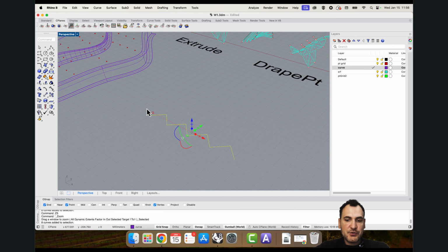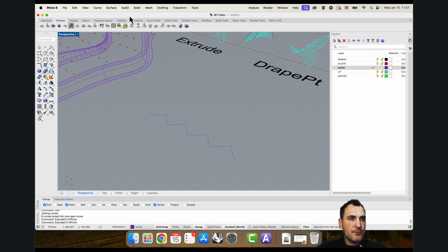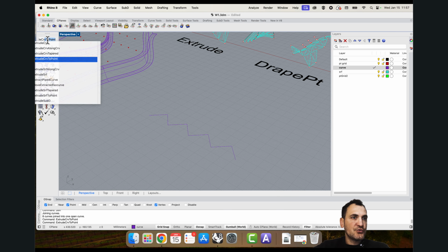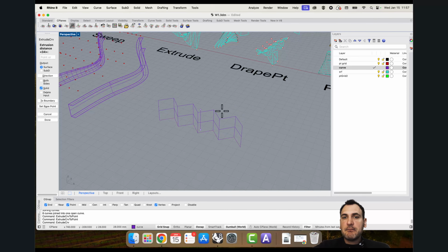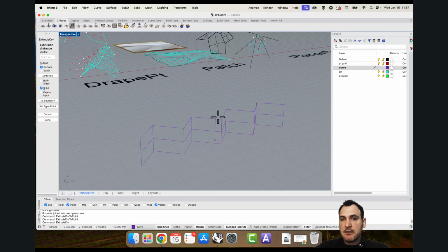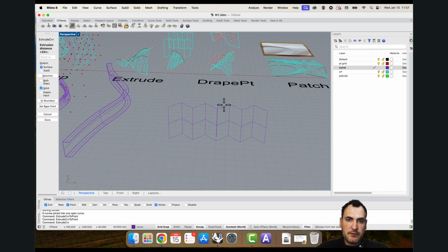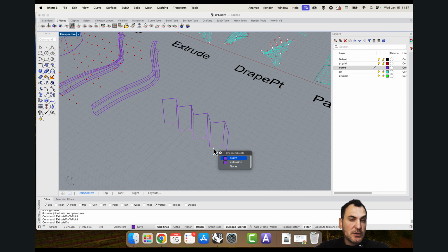And if you join these, and if you do extrude, I do extrude curve. Let's see, extrude curve. So it immediately recognizes the plane on which the geometry rests, and it calculates the direction I want to extrude. So this is kind of a planar curve, and it can register this type of vertical displacement. But you can also do extrusions in other directions.